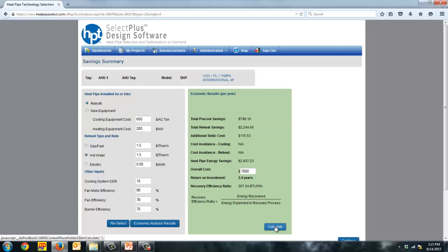Whereas let's say another energy recovery device such as a wheel, you do also need to take into account the pressure drop, but also the motor, purge, as well as potential leakage in your system. So you have to take into account all these factors to calculate your RER. And it's really a true measure to calculate how efficient your energy recovery device is recovering that energy.